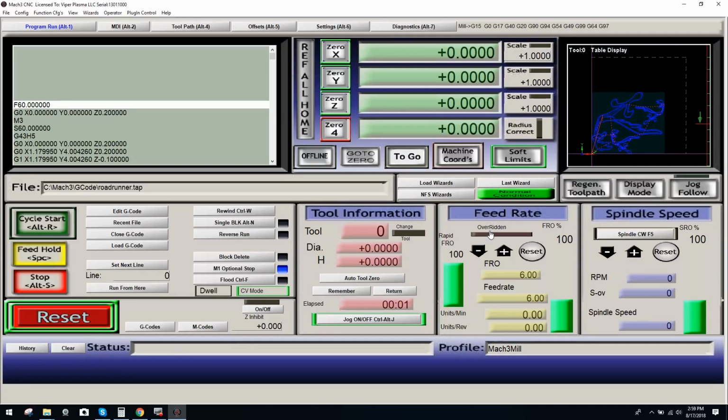And once again, when you're turning off your system, and this is something I've never seen this process discussed, I like to go through the same process I do when I'm turning it on, and as far as validating everything, always validate that you're ending in the same offset, preferably that you entered the system in, which will be default G54. That's my preferred way of actually beginning and ending a session.